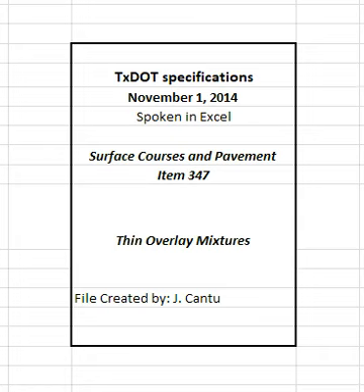If the department's Hamburg wheel or overlay test or department-approved laboratory's Hamburg wheel test results in a remove and replace condition, the contractor may request that the department confirm the results by retesting the failing material. The construction division will perform the Hamburg wheel and overlay tests and determine the final disposition of the material in question based on the department's test results.